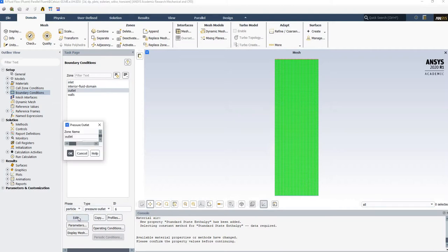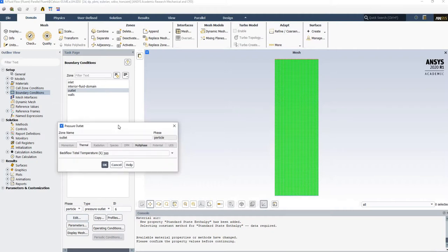So one thing you want to have is, sometimes due to the fluid flow, the particles will go up. And if it is a small particle like ours, you'll see some of the particles will try to leave the domain if you are injecting at a high velocity. In some cases we don't want our particles to leave the domain.